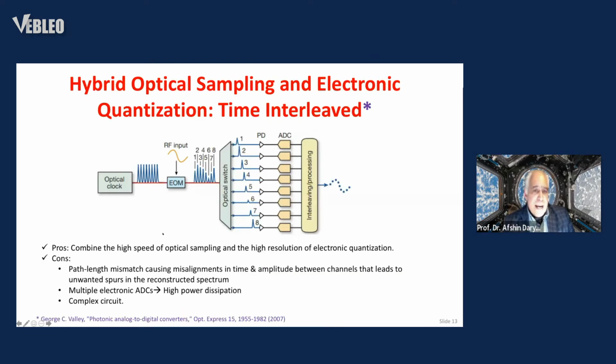To resolve this matter, the ingenuity of time and wavelength interleaving has been used, and you will see that the RF signal in the form of a sinusoidal signal modulates optical energy that is coming in the form of pulses, and the envelope of it is shown here for the short optical pulses that are coming in.